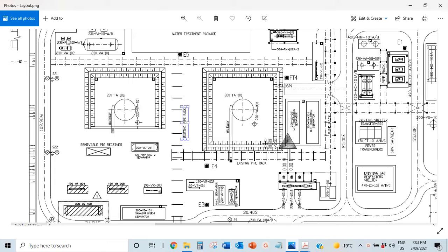What they do is cool the equipment around, because this fire can be so hot that it jumps here. It heats up what's in here so much that this blows up. And when this blows up, it's what you call a BLEVE. That's a boiling liquid expanding vapor explosion. Wow, that's a mouthful.